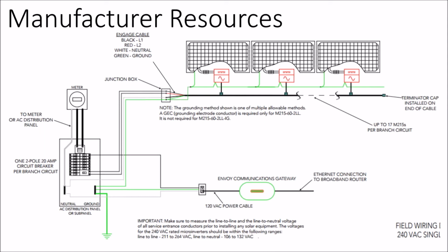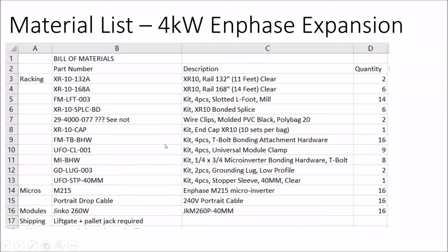And so you call up your electrical contractor and you say, you want to do a solar install? They'll say, we'll let the solar guys do it. But if you call up the electrical contractor and say, hey, we're doing solar, but all we're really doing is running 5 branch circuits up to the rooftop and landing on a terminal block, and everything else is plug and play, then they'll say, I've never done solar before, but that seems easy enough. And now all of a sudden you're getting into cheaper labor that is not necessarily worse labor.